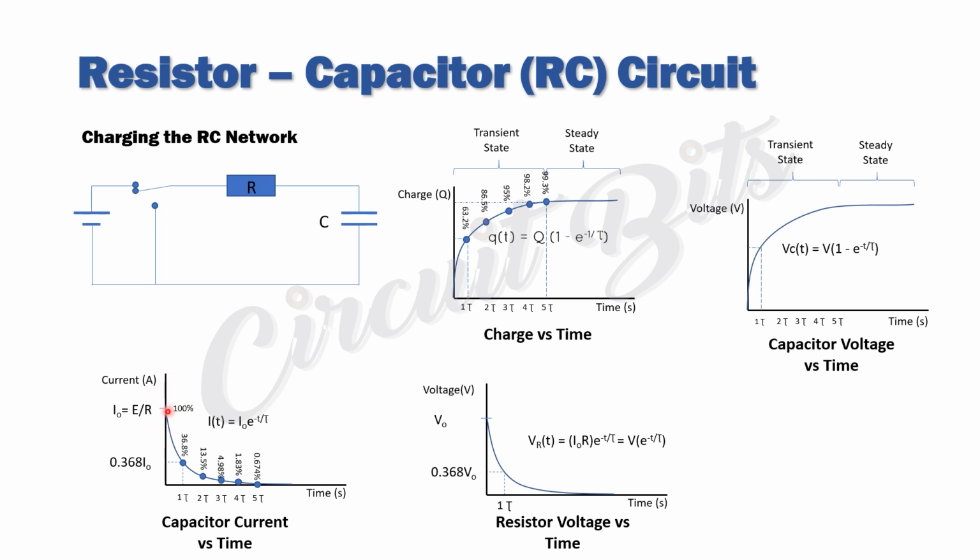You have maximum current flowing into the capacitor from the time you toggle the switch to the voltage source. But then that current continues to drop until the capacitor can take no more. So we can see that at 5 time constants, the capacitor is full, approximately full. So we can use this formula that was given to also find whatever I want regarding how much current the capacitor takes at what particular time and all that.